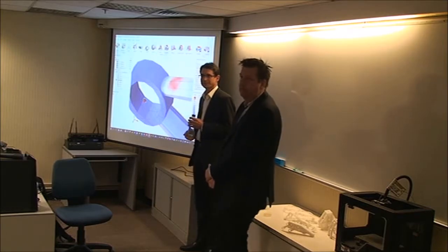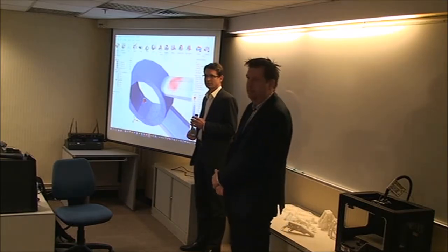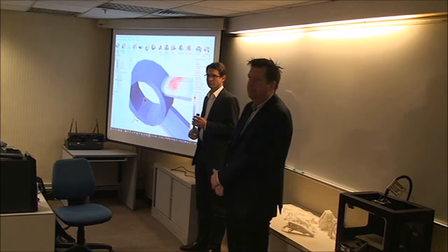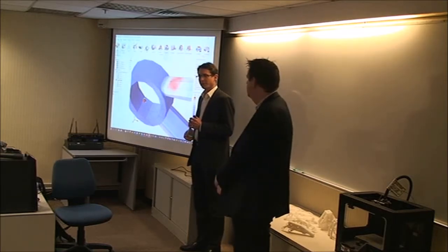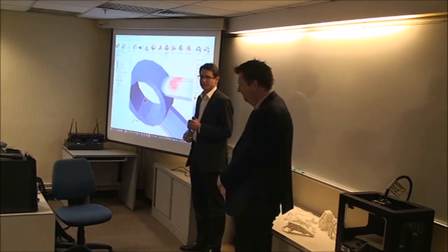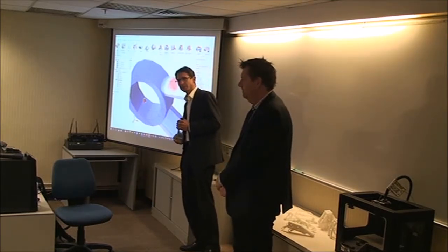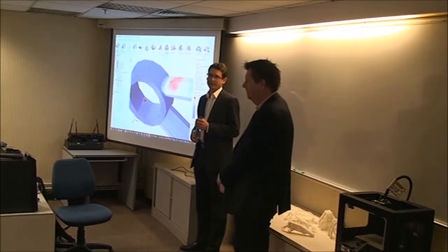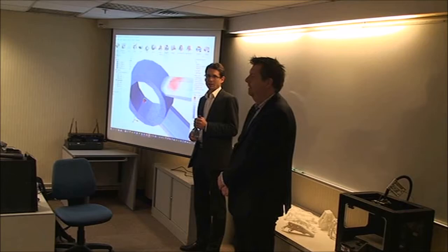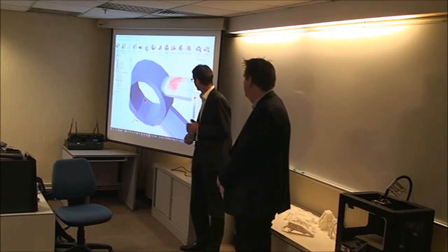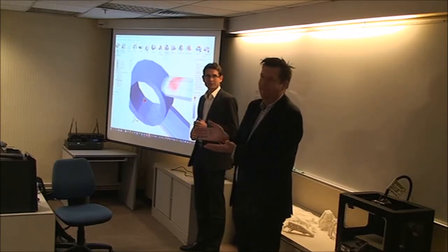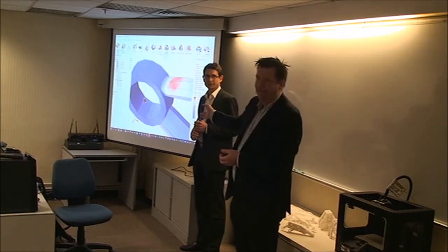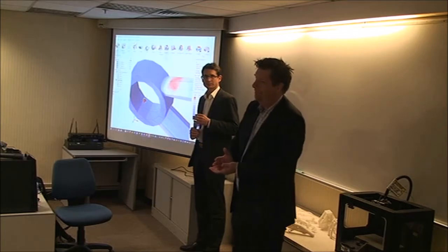We now have a 3D printer that can actually print this component in alloys, such that we can test the material instead of plastic. Yes. But when you print that and bring that into reality, you have to know what the printed material will look like and what that can withstand. It is different to a forged aluminium, for example, and therefore you have to adjust your targets for the stresses. And that can get really complicated because your print direction changes your material properties. So this part might not work if printed in one direction, but could work if printed in the other direction.